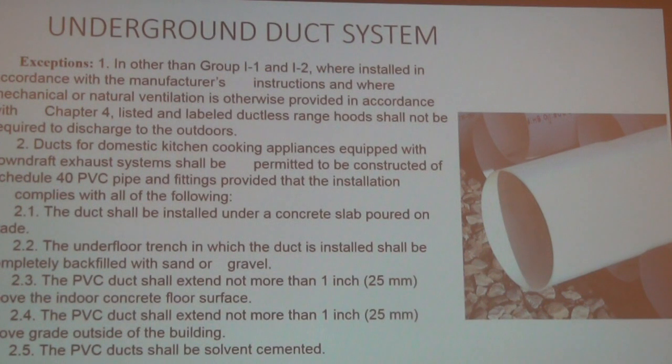Well, most of the downdrafts go down to the basement. The Japanese cooking. If you have a basement. Oh, okay. You see these commonly in restaurants, the table cooking, hibachi style. They'll have drafts going down and they'll be PVC down. But basically, it says that it has to be below grade. You can't use plastic duct above grade.